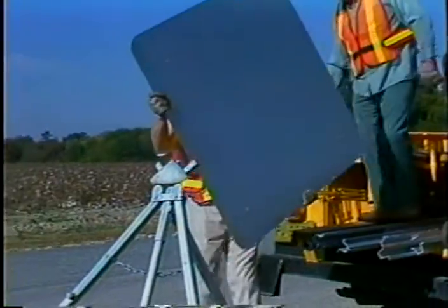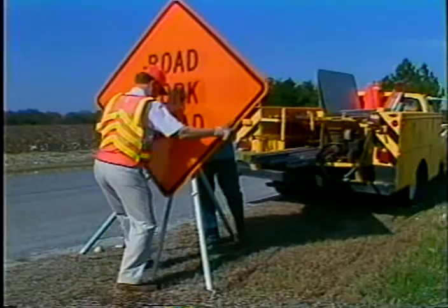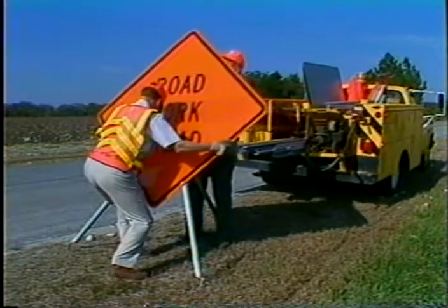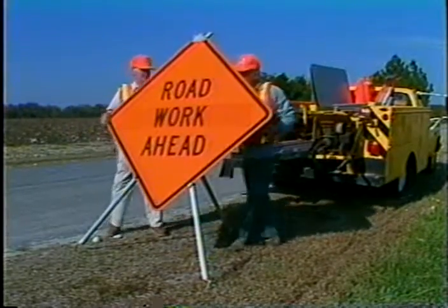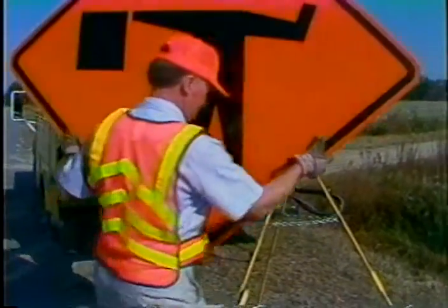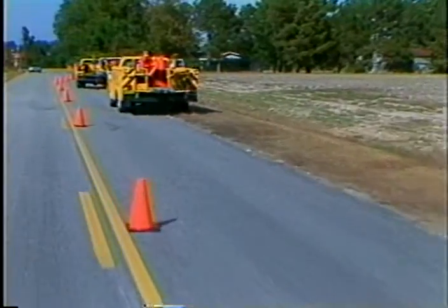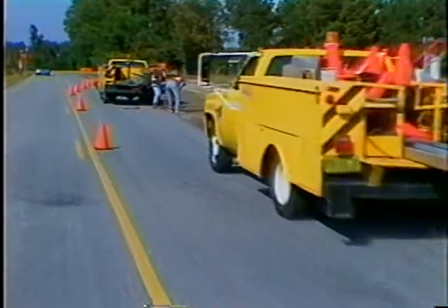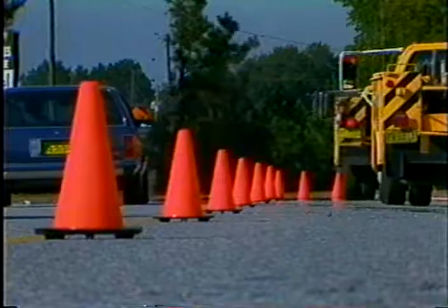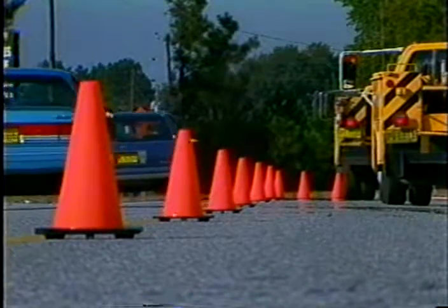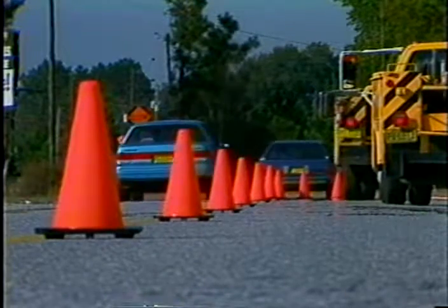You are probably most vulnerable during the installation of the traffic control devices. To minimize this hazard, install the devices before work begins, starting with the first device the driver will see when approaching the area. Then continue installing devices, advancing toward the work area. To evaluate any work zone traffic control, drive through the work zone after all the devices are in place. Difficult as it is, put yourself in the place of the unfamiliar driver, the one who's not anticipating that you're in the roadway.